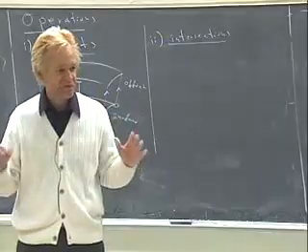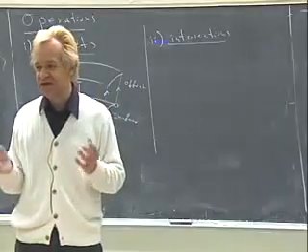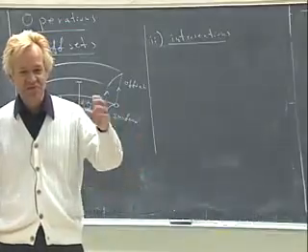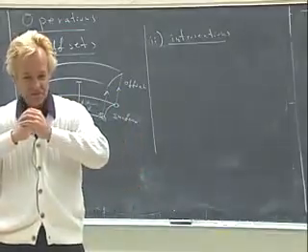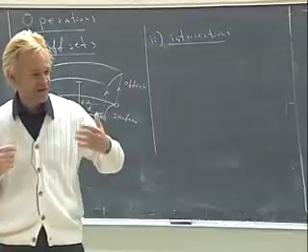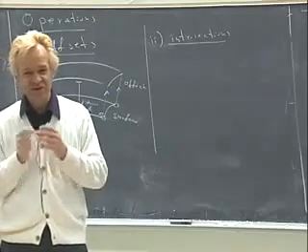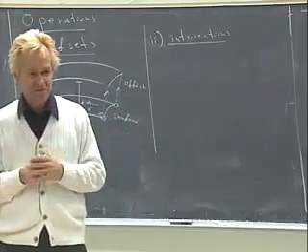The fuselage and the wing of an aircraft are designed independently by independent designers. Ultimately, all of that has to be merged and comes together, right? And then the wing intersects the fuselage, and you have to compute exactly where this intersection curve between the wing and the fuselage is. That's the way it is.